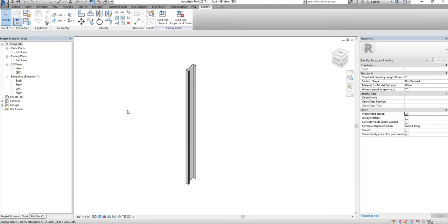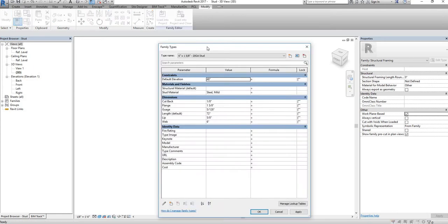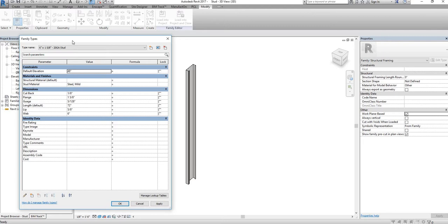The next thing we're going to go over is shared parameters. If you've never used shared parameters before, this can be kind of complicated. But basically what you're trying to do is create a folder of parameters that can be used by other elements or other Revit families as well as projects. Think of it as a basket of parameters that you can choose from that all families and projects can see as the same language. I know it's kind of complicated to understand if you've never used it before, but I'll go through that with you and you can see what I mean.